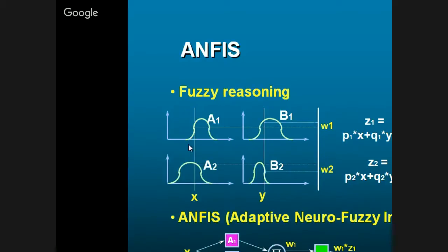And again you give the membership function, like you define the membership shape for it. It may be a triangular membership function, it may be a trapezoidal. You have to see according to your problem how it is varying and choose it. Similarly for the other input, Y, you have defined two membership functions, two linguistic variables, B1 and B2. Say Y is moisture, low moisture and high moisture.